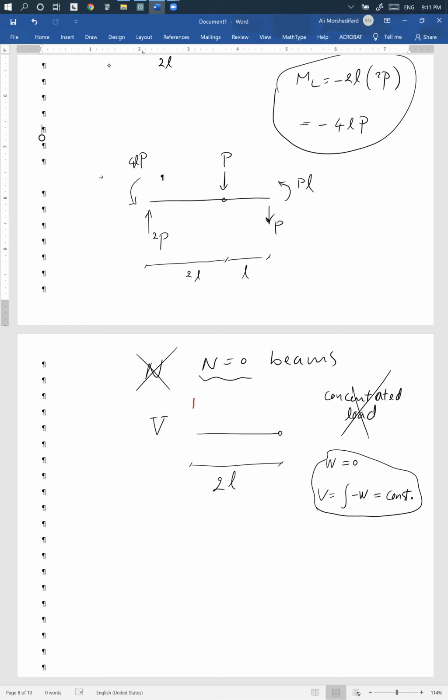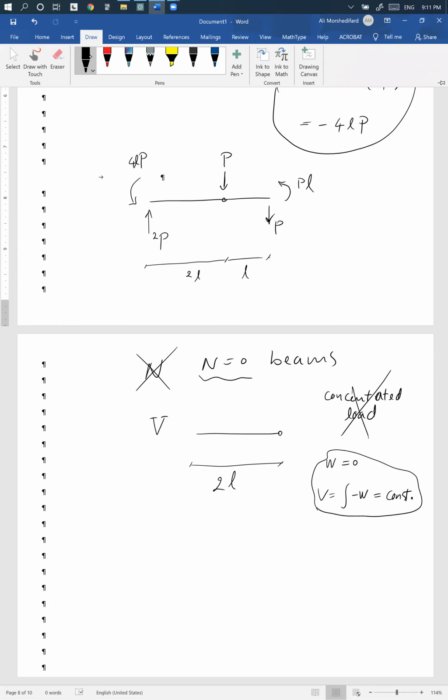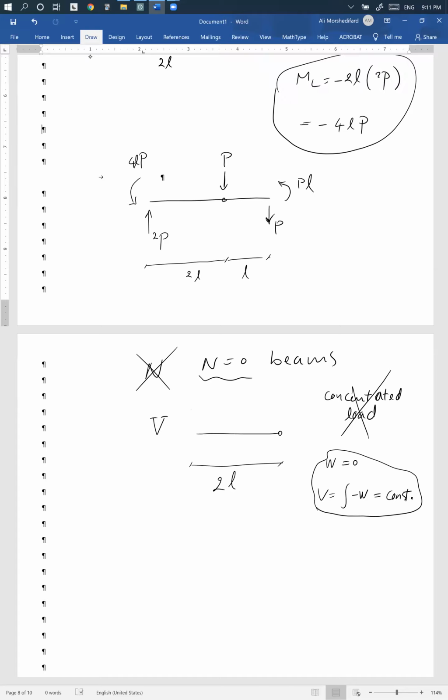So I know that this is my coordinate system. Again, I'm going based on my own thing, but for beams, you can just memorize the lecture convention. That's also totally fine. So this is my coordinate, t hat is in the negative direction, so this is the direction of positive shear, right? So you can see that 2P is in the direction of positive shear. Nice. So I have the shear in this whole segment, basically without doing any calculation.